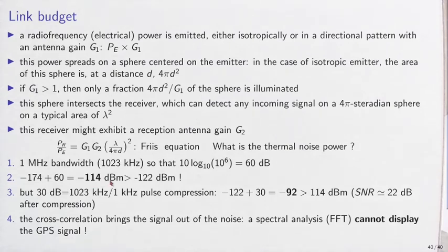So thanks to the energy collapse into the carrier, when correlating or when squaring, we see that the signal rises over the thermal noise. So from this presentation, we conclude how we have addressed the benefit of correlating for improving the signal to noise ratio, for accurate time of flight analysis using correlation. The width of the correlation peak is equal to the inverse of the bandwidth.